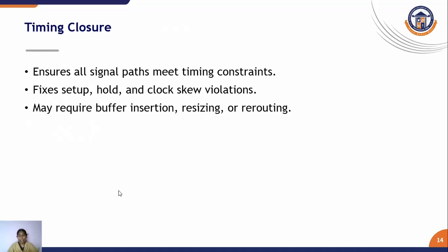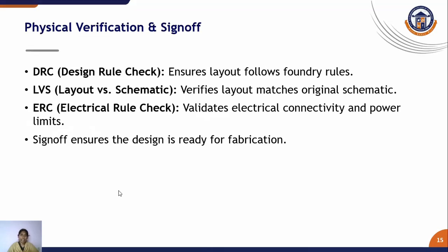Once everything is completed, next we move to physical verification and sign off. Here we check DRC, LVS, and ERC. DRC means design rule check. Here it ensures the layout follows foundry rules. LVS means layout versus schematic. Here it verifies the layout matches our original schematic, that is our circuit.